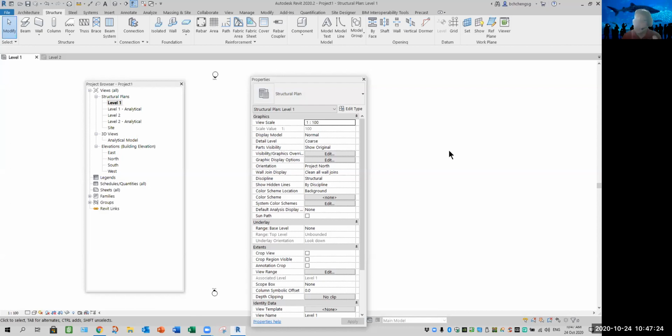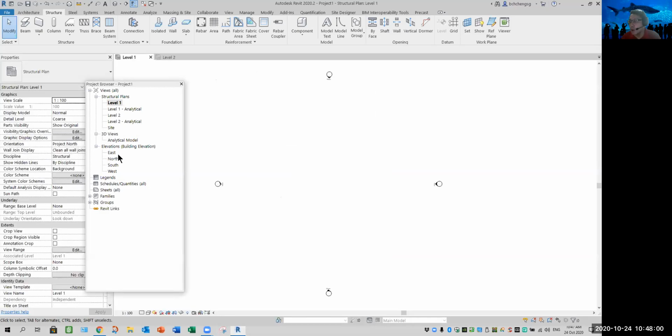For me, I just keep it open. That's where I want it. To dock to the left, your mouse pointer should select closer to this corner. So left click, hold, drag, and touch the left bar here. See the pointer touch? In 2018, you don't see a blue panel, it's just a transparent frame. In 2019, you see a blue panel. The moment you let go, it docks.